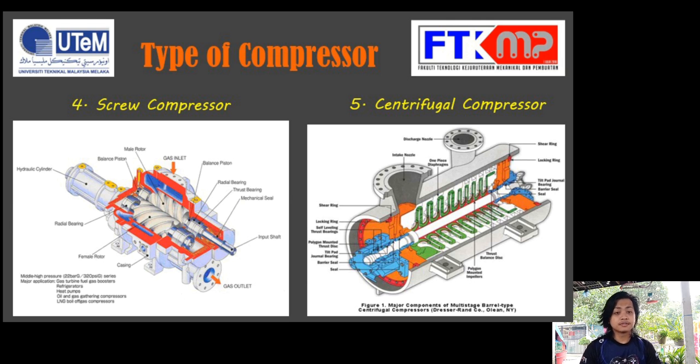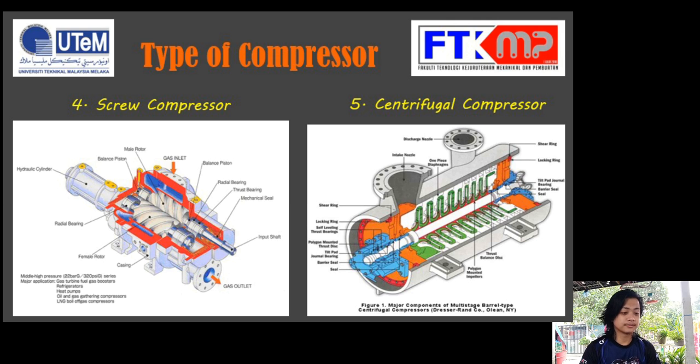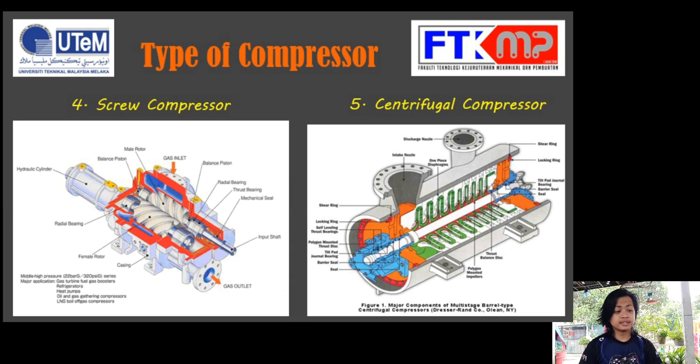The advantages of the centrifugal compressor are, first, high reliability. Second, install cost is lower due to small size. Third, low maintenance cost. And lastly, no oil contamination. Disadvantages of this centrifugal compressor: first is low efficiency, second is that it is very sensitive, lastly it is not effective for low molecular weight gas.